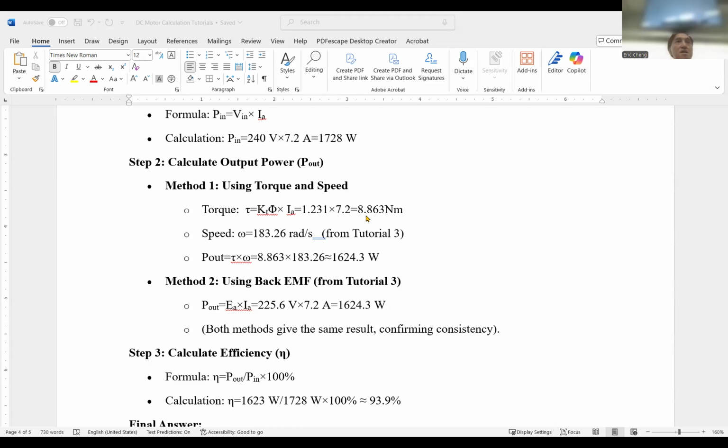This is the same as our previous notes when we talked about the PWM chopper applied to a DC motor. So part B: if the motor is stationary, that means it's not moving, so omega must be equal to 0. Then the back EMF is also equal to 0. Calculate the average armature current when the duty ratio is 40%. Now the motor is stationary, not rotating, EA equals 0. Then we just have a simple resistor in the circuitry. The total input voltage will now be applied to the motor resistor.